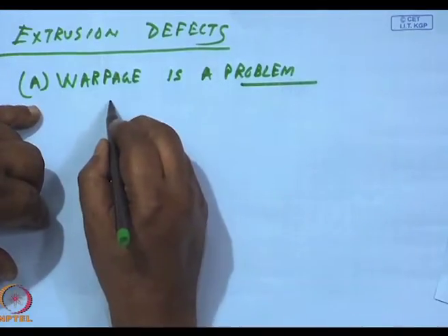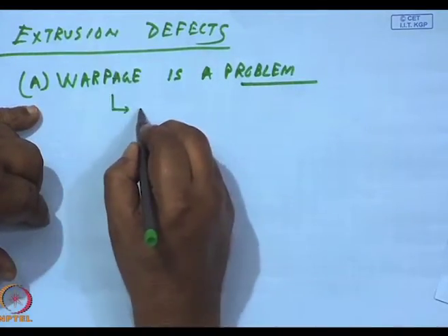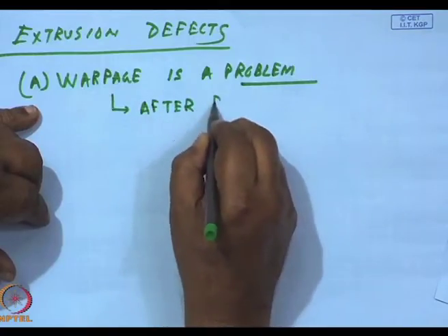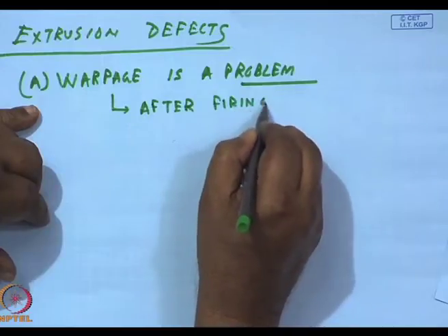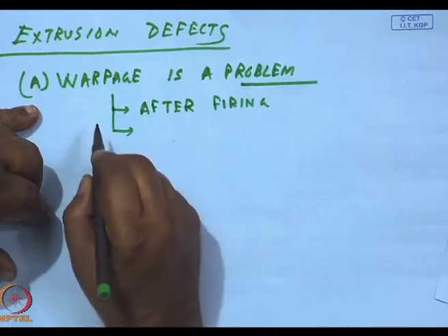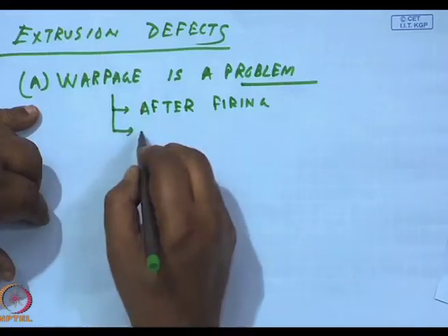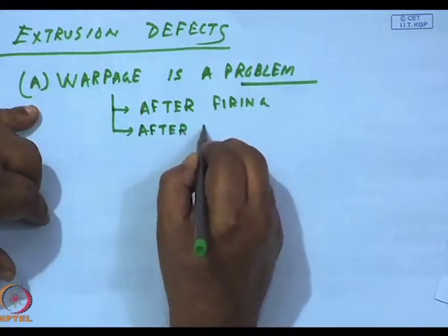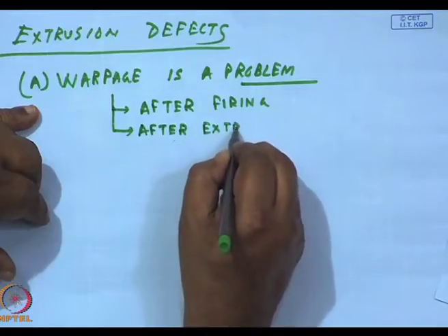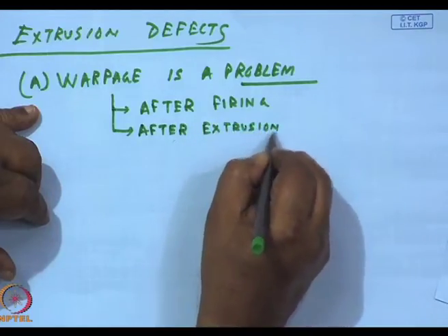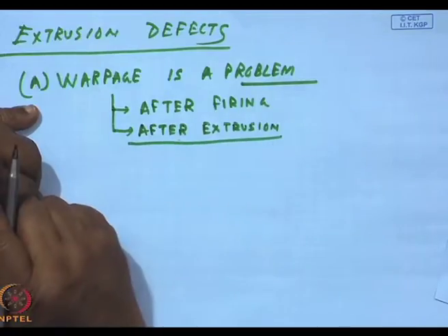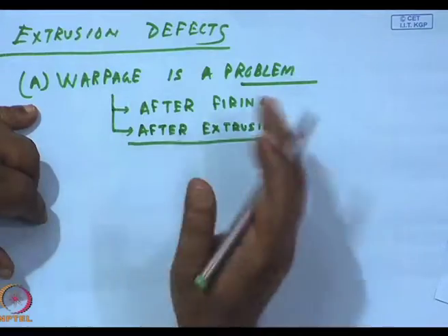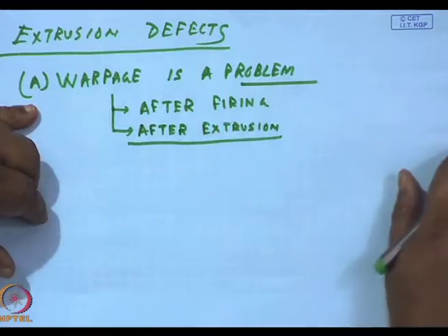Warpage is a problem after firing, and also it can be after extrusion itself. I have not even gone into firing. This can all happen if the mixing is not very well done.